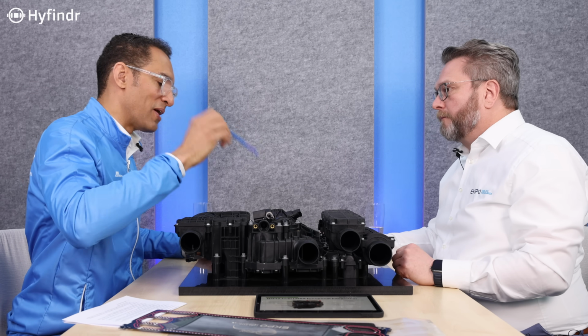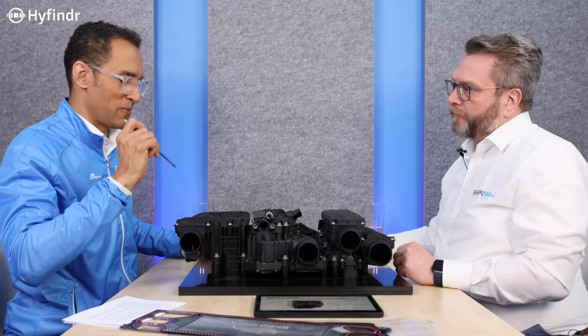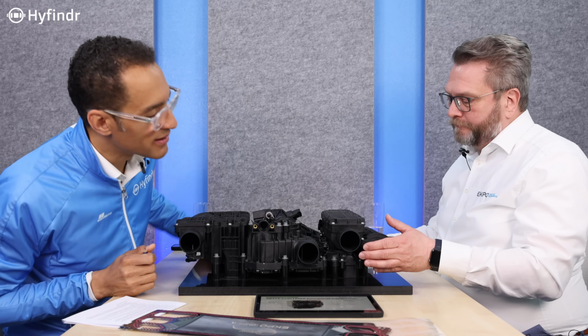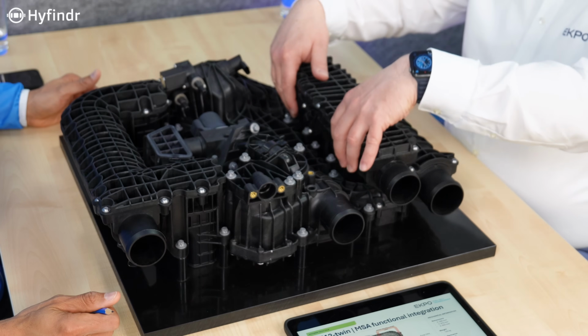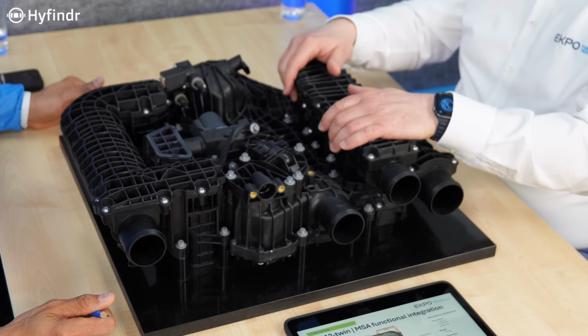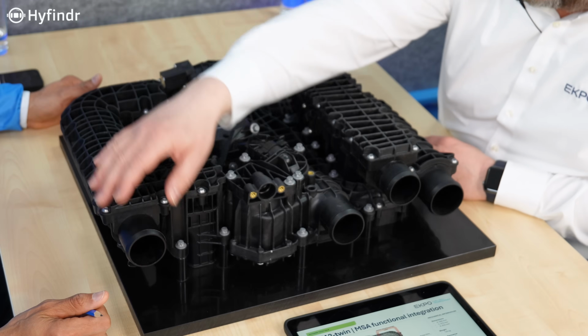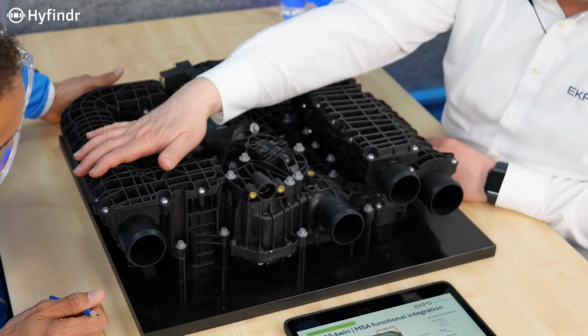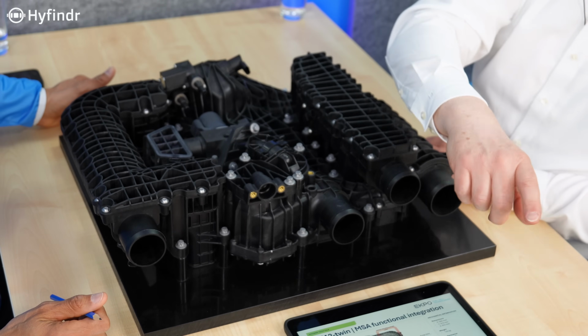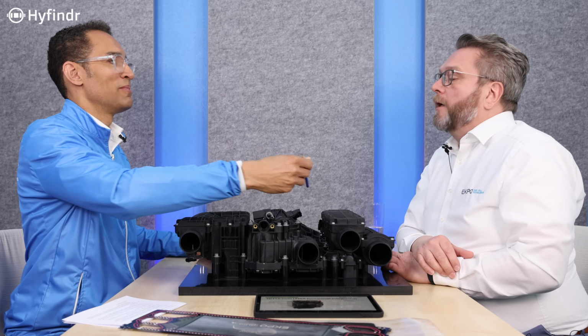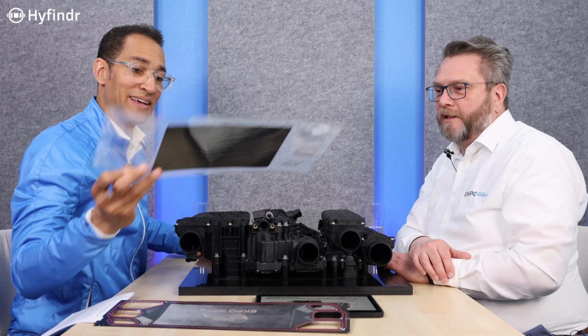Okay, quickly to the other loops. So what about the air? Air is coming in here. It's then distributed underneath to both stacks in parallel, so we have to supply both of them perfectly. Then it's coming back from the stacks and exiting here, and this is now filled with water because of the reaction. It goes into a so-called humidifier, which transports the water into the stream of the fresh air. So you want warm, wet air coming in. Exactly. This is all for the membrane, because the membrane likes to be completely humidified. That's this one here, taking care of this.